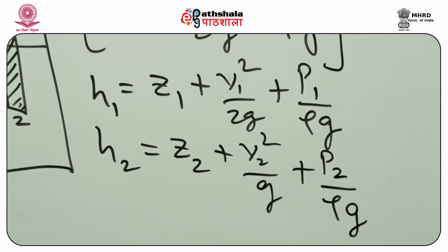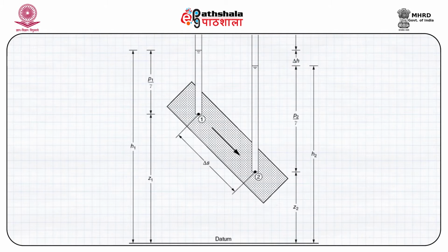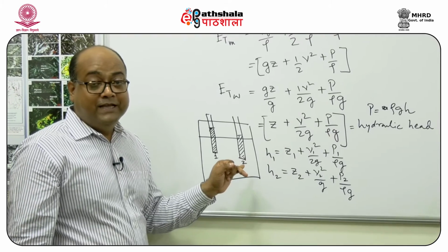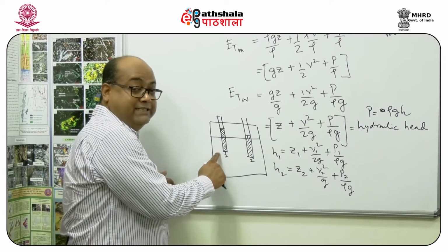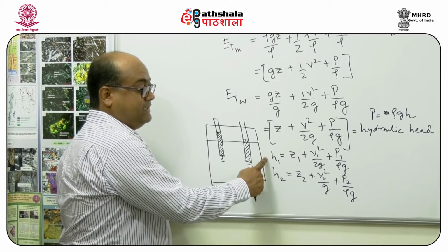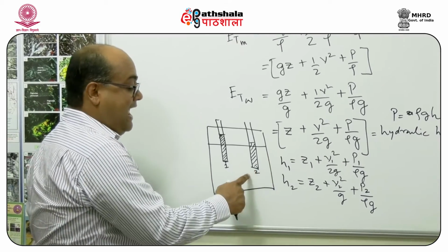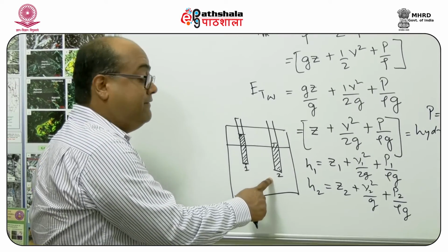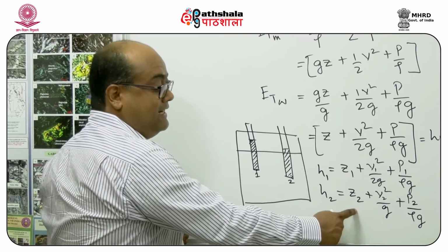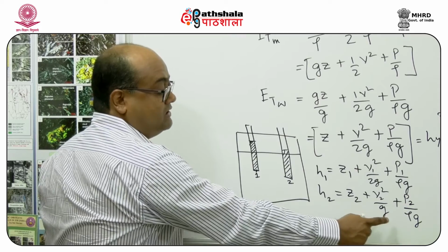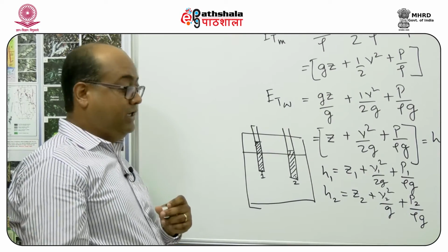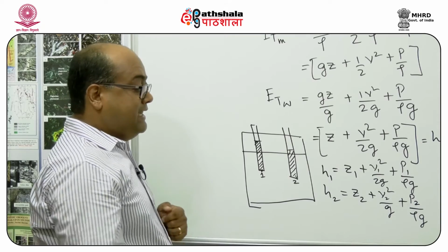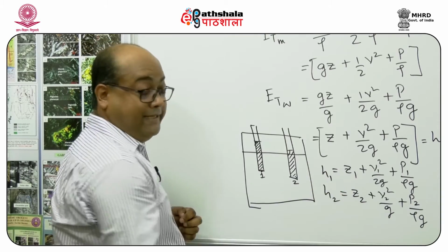So you can see here that the water that is going to flow from point 1 to point 2 of the aquifer depends on the difference in the energy present at point 1, which is represented by H1, and the difference with point 2, which is again defined by the elevation, the velocity and the pressure at these two points. Now, how are these measured?